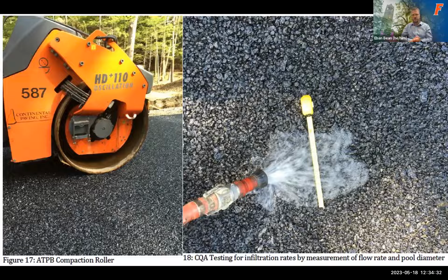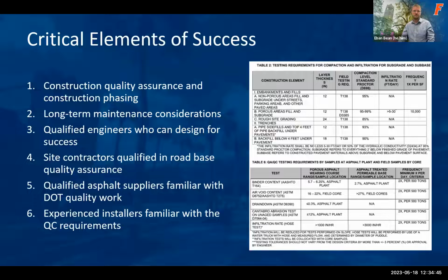You can do this. There's also a single ring infiltration test. In this case, they're just opening up a fire hose and looking at how wide that pool diameter is on the surface for it to basically completely infiltrate.